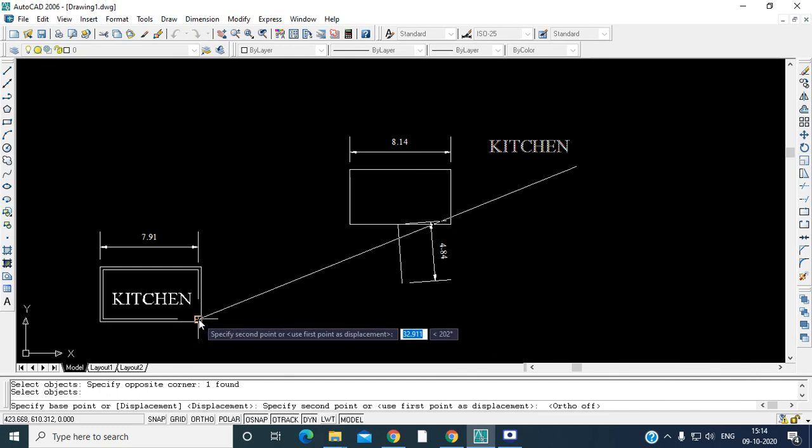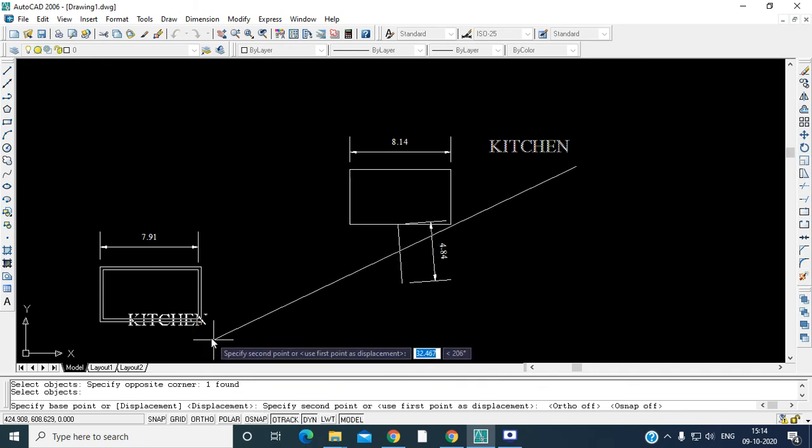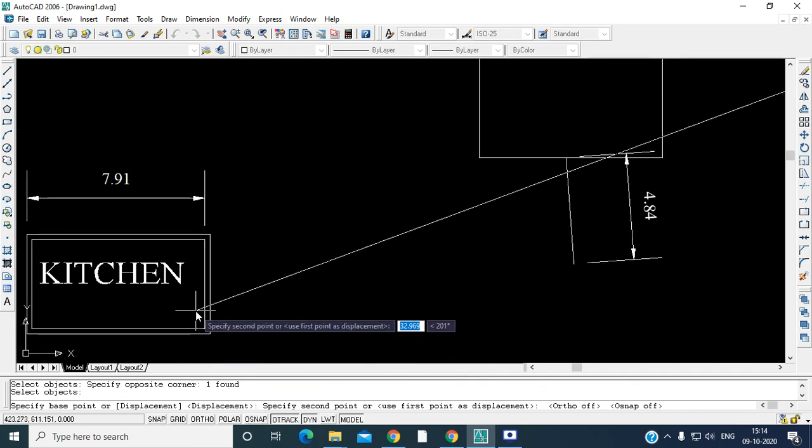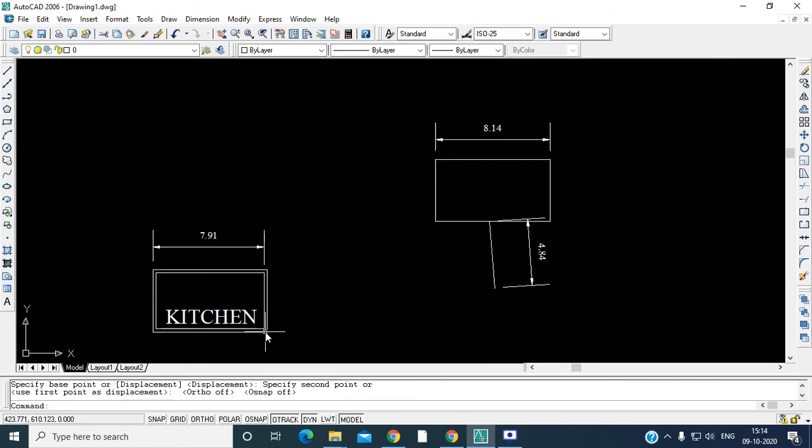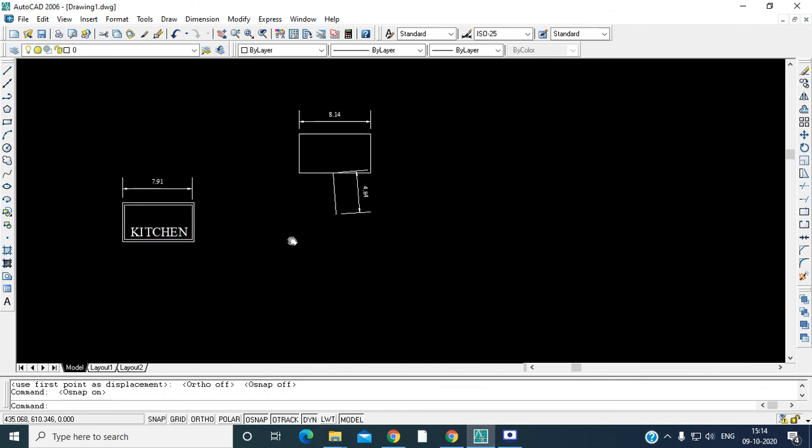Now if you do that, this object will be placed along this line. So you can quickly go back here, turn off object snap and place it anywhere you want, as close to this line as you want. If all object snap was on, then it would have prompted you to put that kitchen in this corner itself. So like that, you have to turn it off and turn it on whenever it is necessary. That is about M text. It is used most of the times in your drawings. So these are some of the commands which you will be requiring.